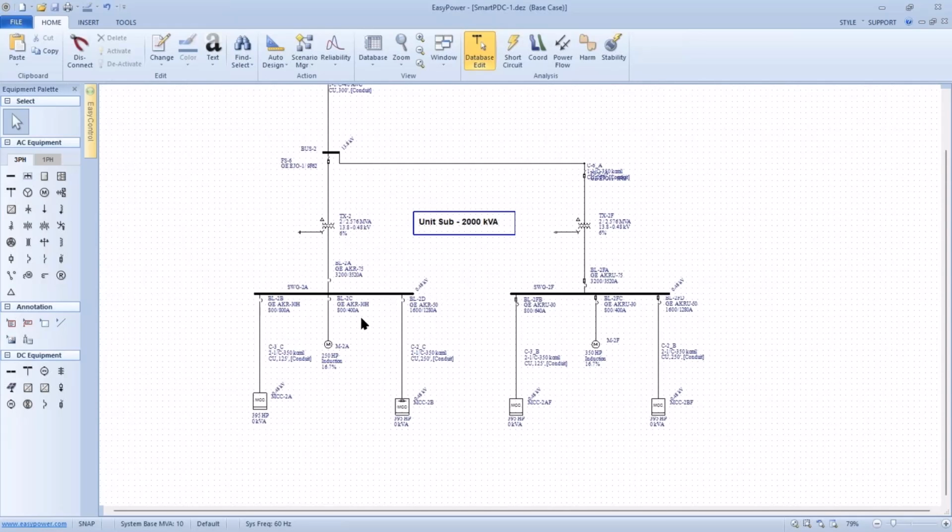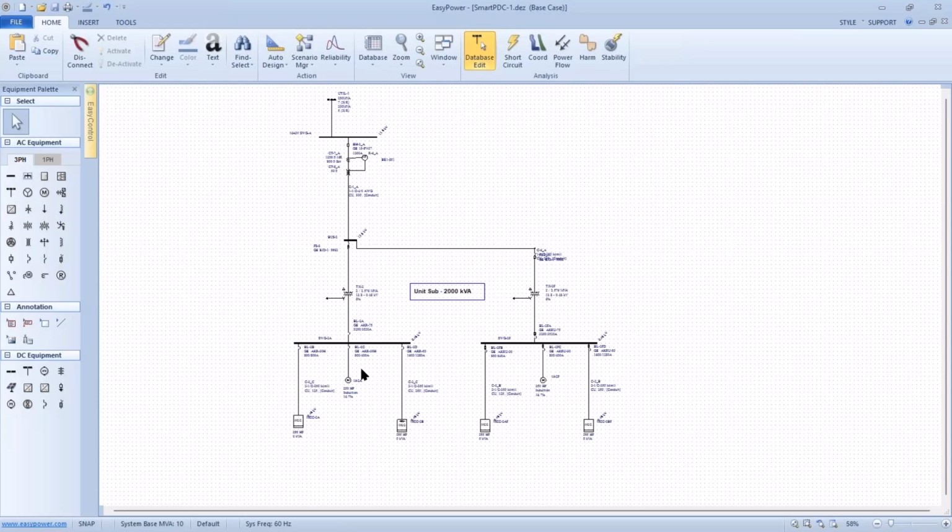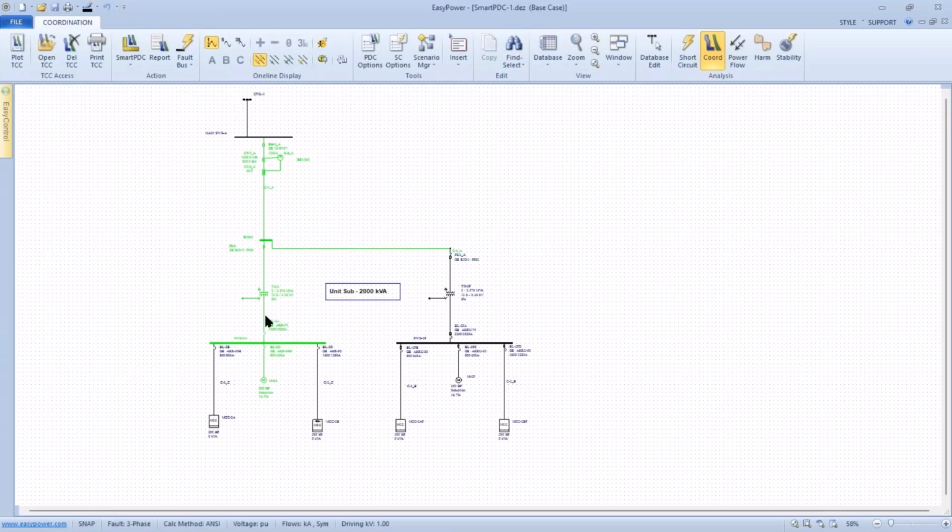But in terms of coordinating for this bus, I want to pick out the largest load, which is the motor. Left click and drag. Pick out the next two or three levels of voltage protection and current protection. Go to coordination. So now I'm coordinating for the switchgear bus 2A. I just undid it, so I'm going to redo it.